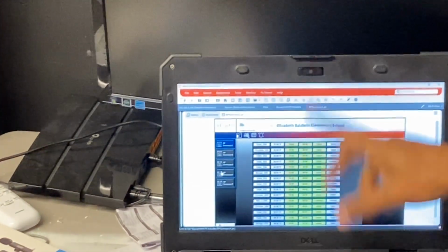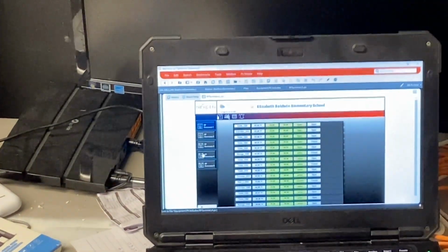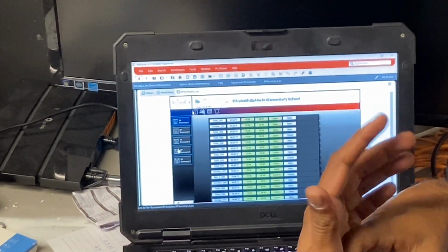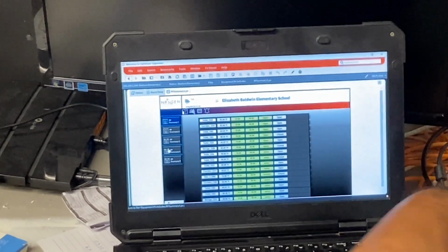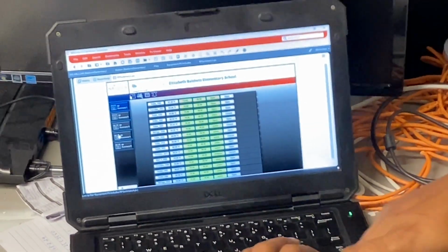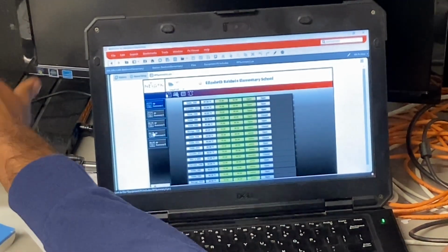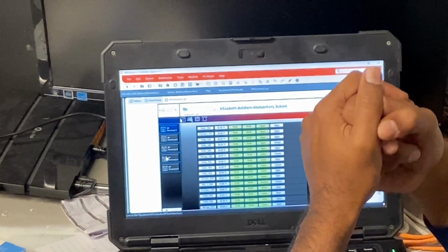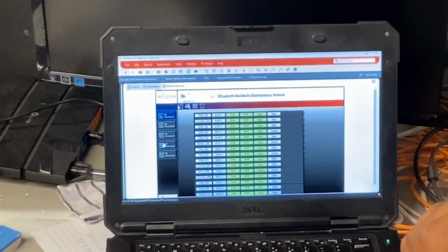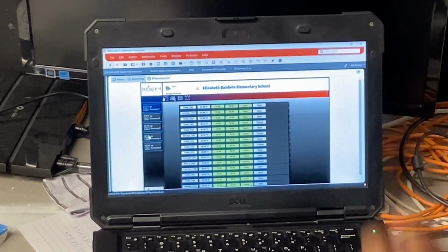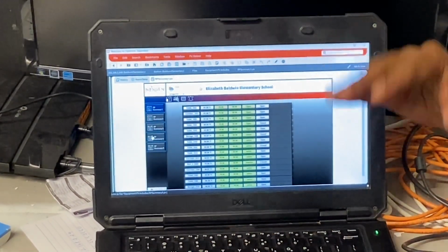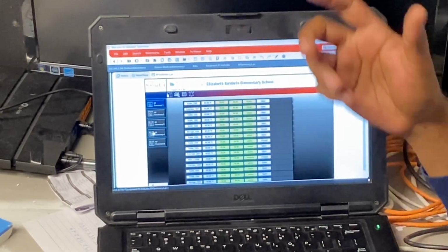As we talked about, the radiant panel is the same thing, but it has a blank plate sensor and you have the set point from here. And the VAVs, you have the display. We can restrict this based on your need, whether you want to give the user permission to override from the classrooms. Teachers can override right now, it is dual: they can do it and we can do it. What kind of swing are we giving the teachers on the thermostat? 68 to 74 right now. So either we can change the limits or we can restrict the permission. That's customizable.